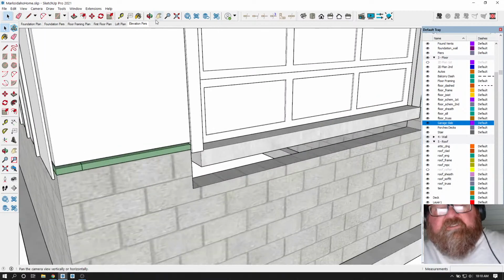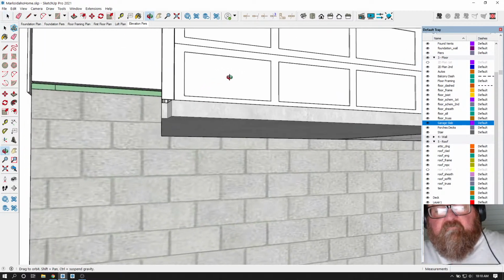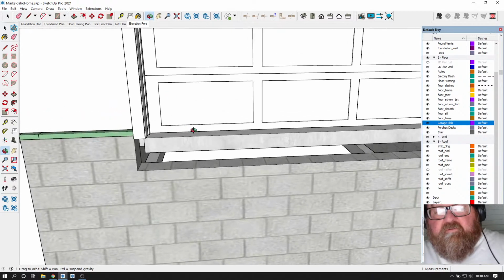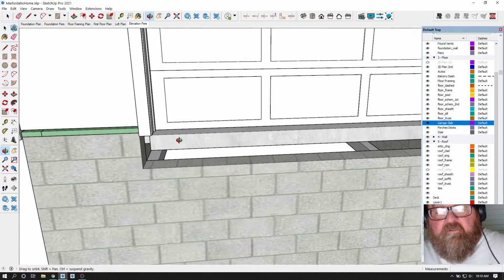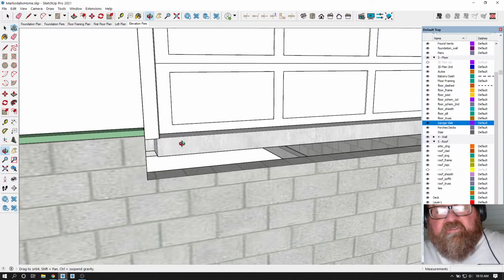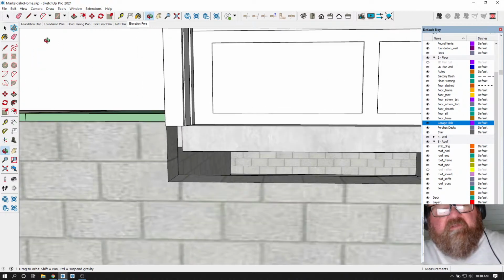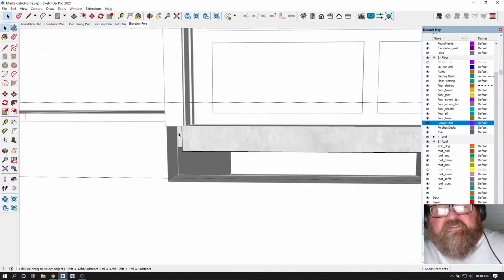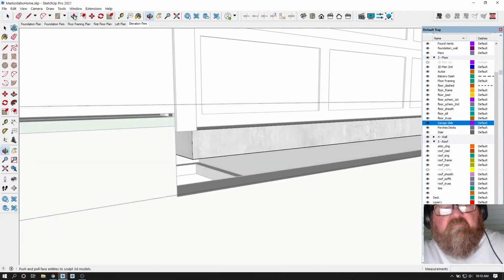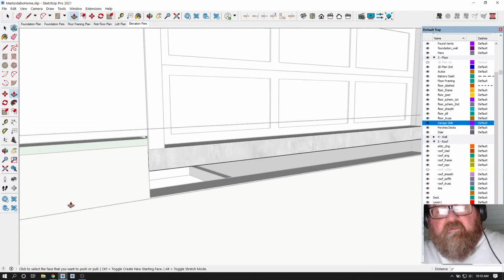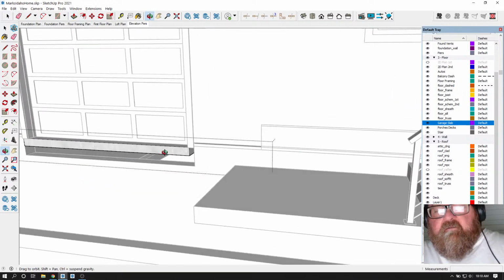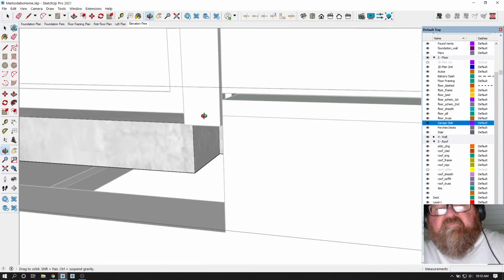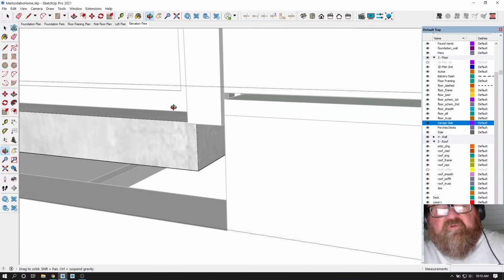And I think we adjusted, I don't remember. Oh, I know what it was. I know what happened here. I moved the block opening over 6 inches for the framing. So I need to fix that. I like the framing to come down on the inside of this block when you have this condition, so that you'll have something to nail a trim to.